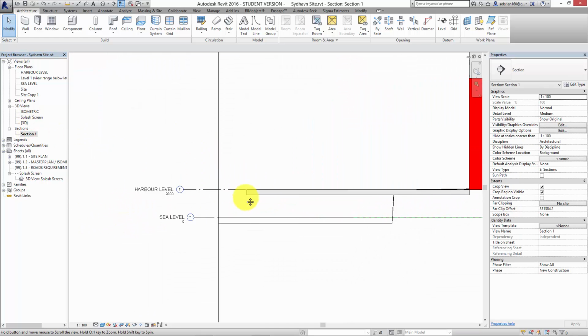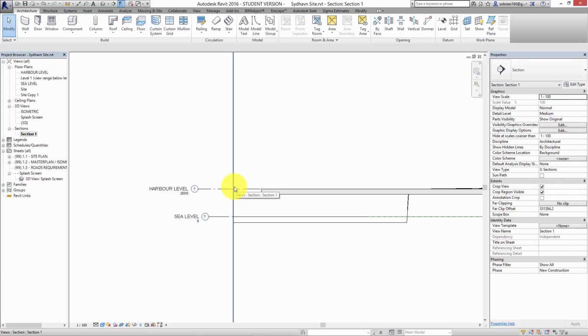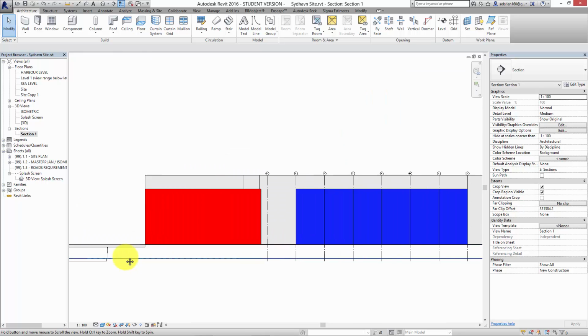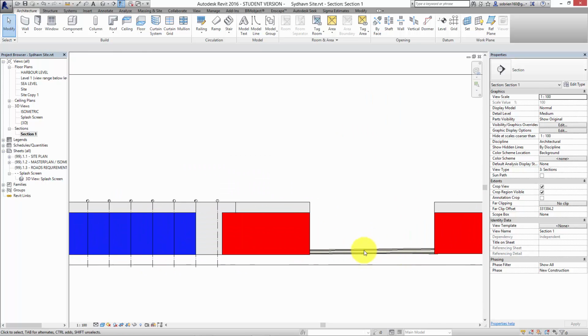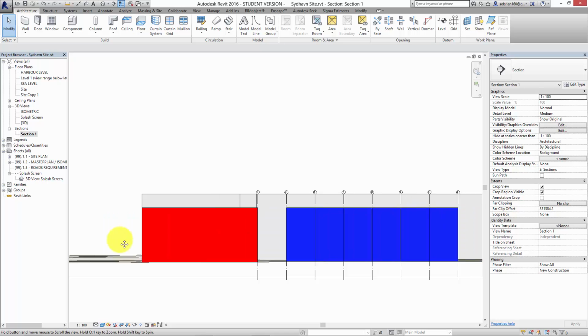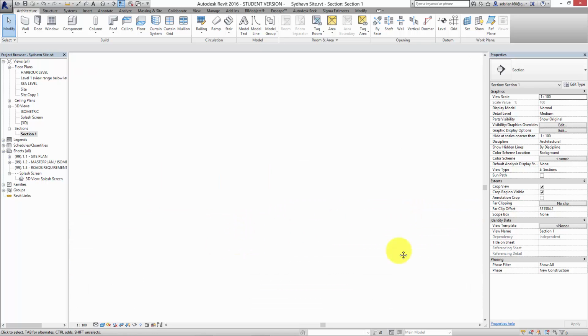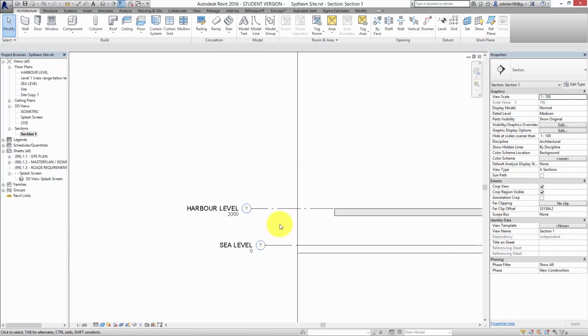So first we need to figure out, because we don't have it over here, but over here, the guidelines for the local area plan as to how the public spaces want to be treated. Where's the tree line, where's the pathway, where's the road, where's the cycle path, all that kind of stuff. So you have to take that into account, because we have these basic levels from the Ordnance Survey map. And you can see there's a vague slope in the model I've given you, which is the way it is.